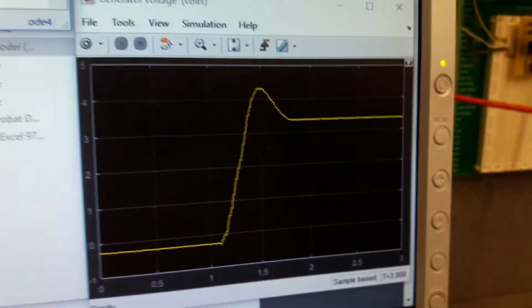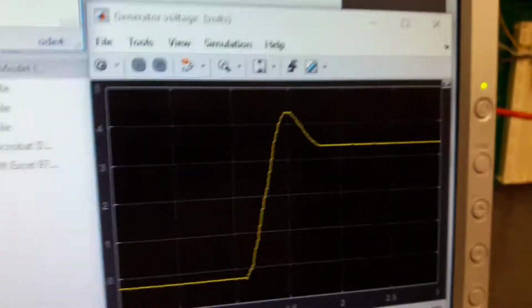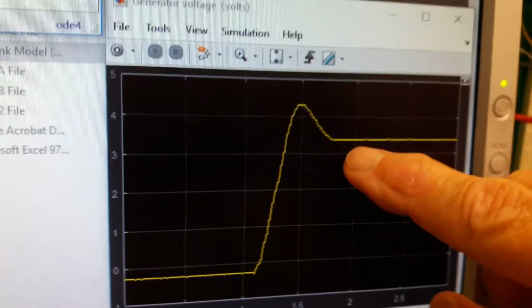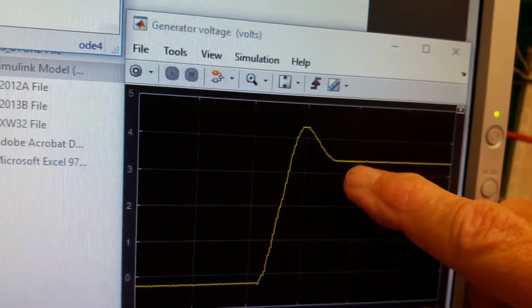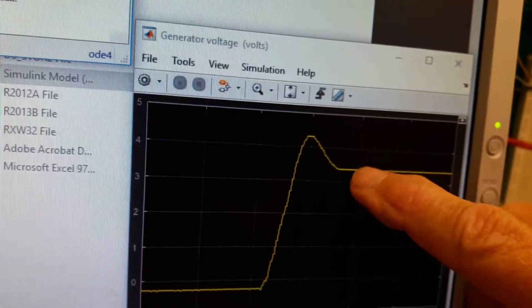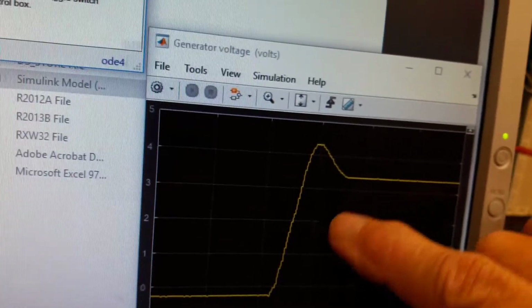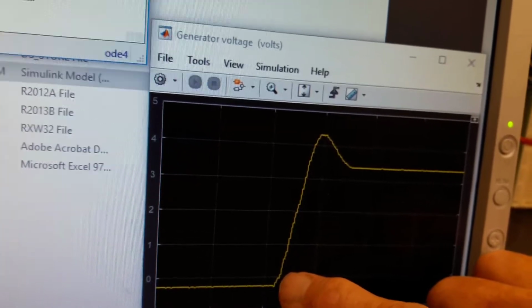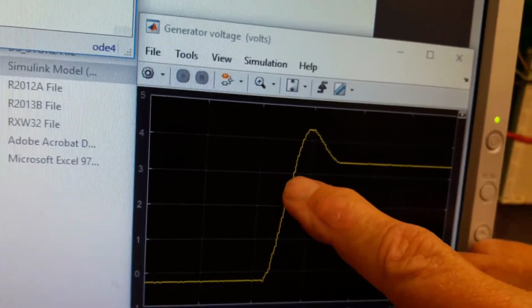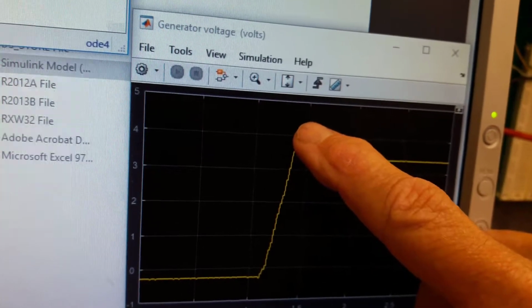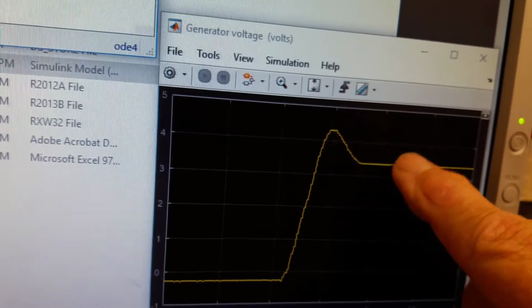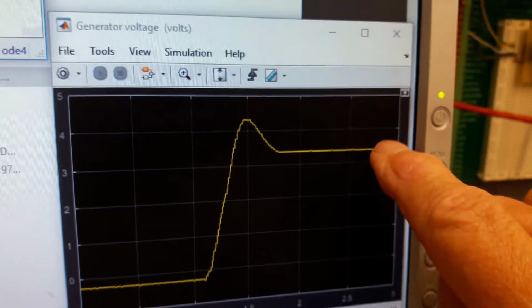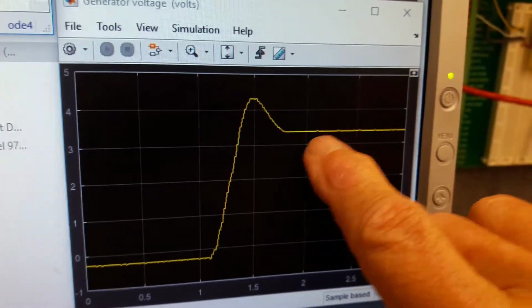Let me say a little bit more about that before we go forward. The actuation signal that comes back depends upon how far off you are from the final value. For instance, when we're down here, we have a big actuation signal that moves the Motomatic to a new position, and we come up here, and since this is a second order signal, we should see some swinging back and forth with a decreasing magnitude because it's a second order underdamped system.